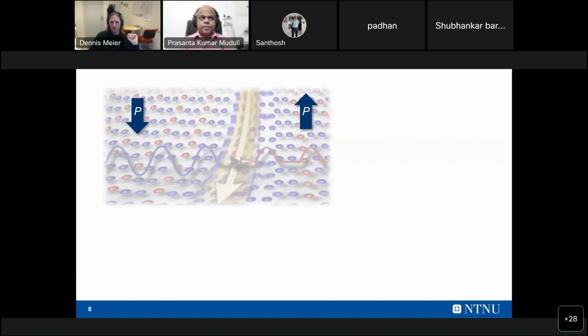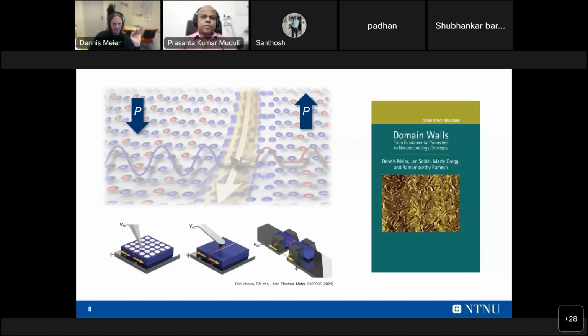So it is almost impossible nowadays to list all the different interesting studies that were published. But what I would like to point out is that a lot of techniques were developed over time that allowed us, in the first place, to study these properties. Early on, people started to put electrodes on top of the domain wall and measured the transport properties, and then compared that to electrode pads sitting in the bulk to see that there is enhanced or reduced conductance. Of course, scanning probe microscopy became one of the most widely used tools, because you have this sharp tip and then you can measure conductivity, piezo response, and other effects on the walls.